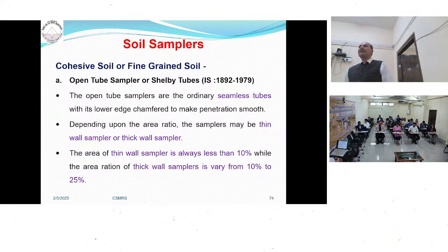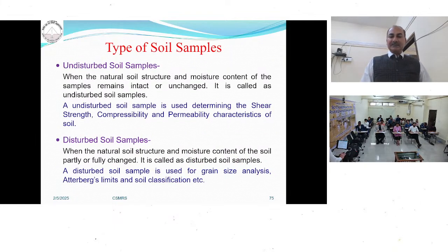So now you are collecting the sample. Suppose you are collecting it in a thick sampler. What will happen? The sample is disturbed by the way you send it for testing in the laboratory. When taking it out, there is some more disturbance. So whatever results you are getting are not truly representative of your data. It could be high, it could be low. So while collecting a sample, this is a very small thing. Your sample should have the proper dimensions, proper thickness. So I will tell you how it changes.